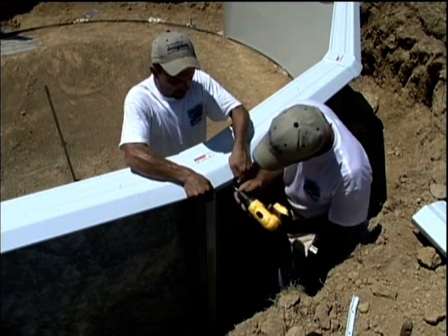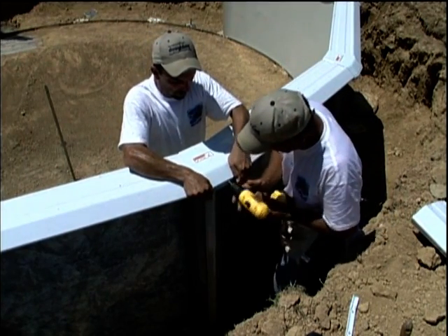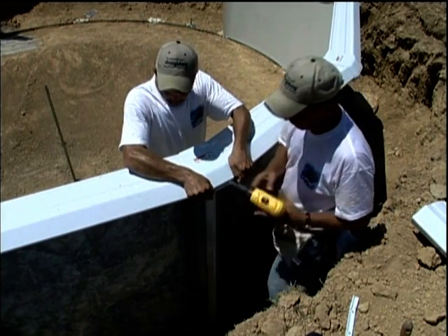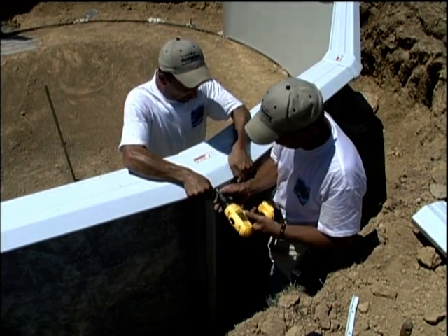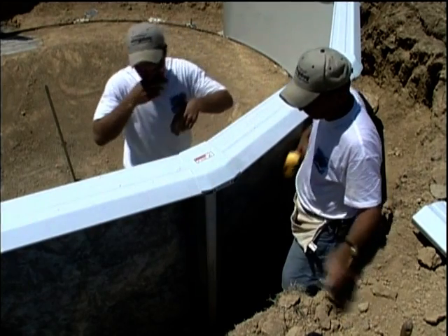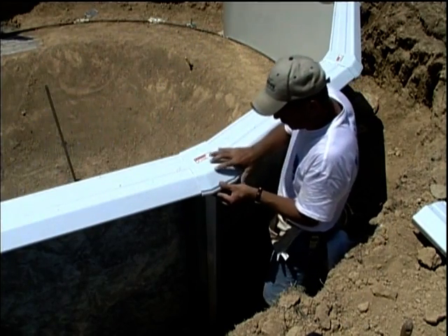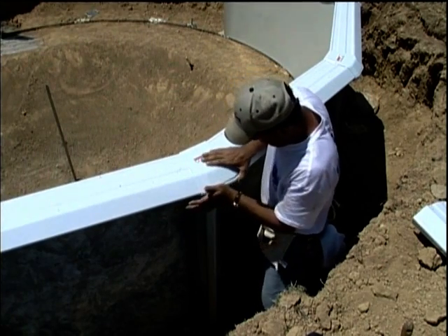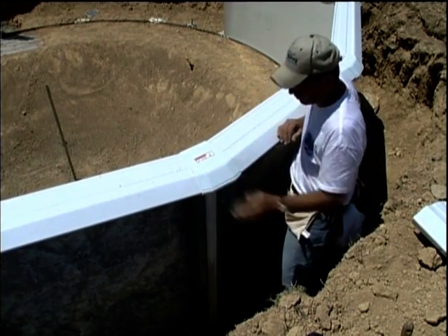By pulling up on the bottom connector and pulling forward and down on the top connector, the holes in the top and bottom should align. The small holes will appear behind the large holes. Then fasten together with 2 10 by 3/8 inch long sheet metal screws. Finally, snap the plastic trim piece into the 2 large holes.